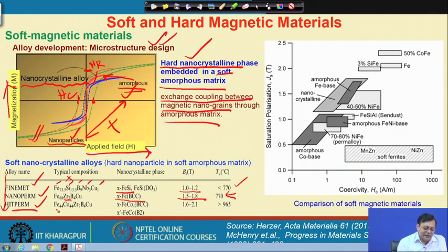Whereas in the Heatperm alloy, here the iron and cobalt both are 44, meaning equal stoichiometry, and zirconium is again present and boron is present, copper is also present as in the Nanoperm alloy. So, the only difference between Nanoperm and Heatperm is that I am substituting 50% of the iron by cobalt. In that case, I have again iron cobalt alpha phase, which allows a much higher saturation value, because we achieve a higher value of the Bohr magneton, and the temperature of use could reach up to 900 degree centigrade or higher than that, and that is the biggest achievement so far.